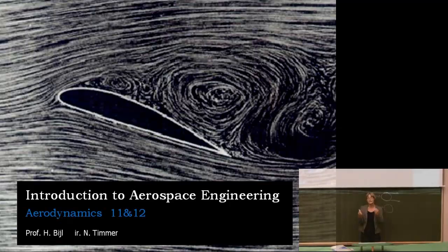Turbulent flow has more energy inside the boundary layer. You can see that already with a thicker boundary layer, right? Closer to the object, there's more speed, so more energy. And that's due to the fact that you have small scales, sort of small eddies in all directions. Turbulent flow has more energy to fight the adverse pressure gradients. So what will happen is it will separate later, for example here.